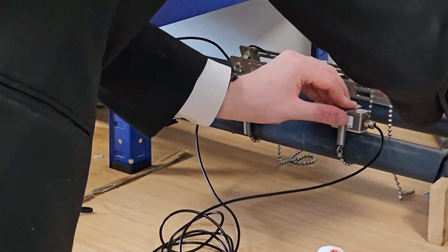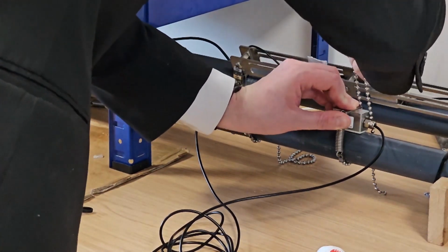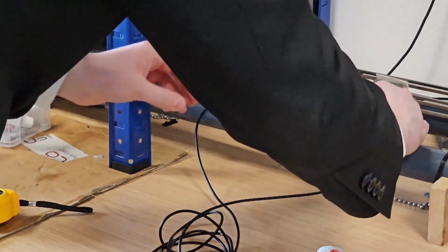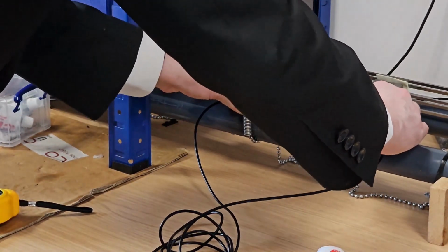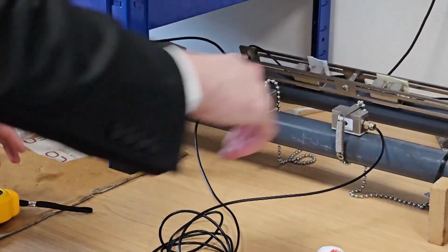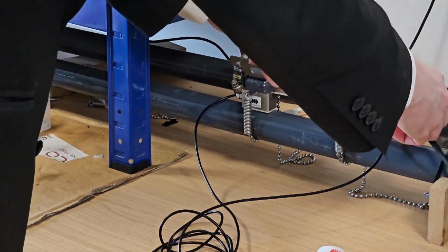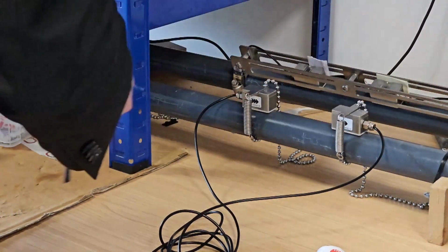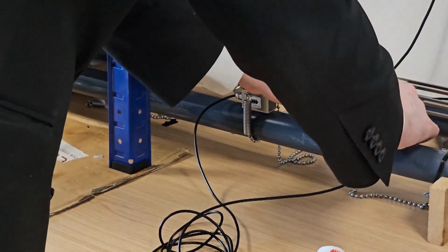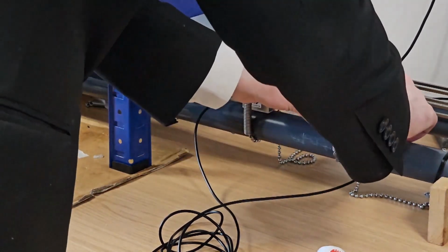So I'll fasten this on, get it in place. It's quite important to make sure that the transducers are as well aligned with one another as possible, as they'll be transmitting ultrasound and receiving, and if they're misaligned you might miss those reflections. So I'll measure again. I'm slightly further apart than 89.5, so I'll just give it a small nudge forward.